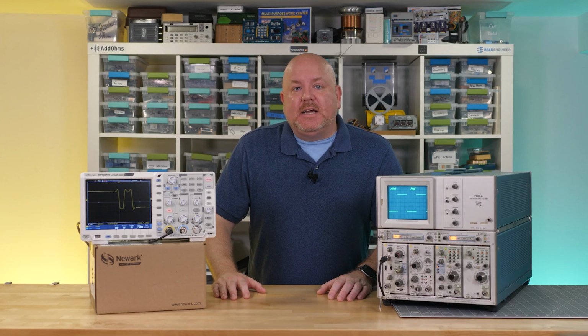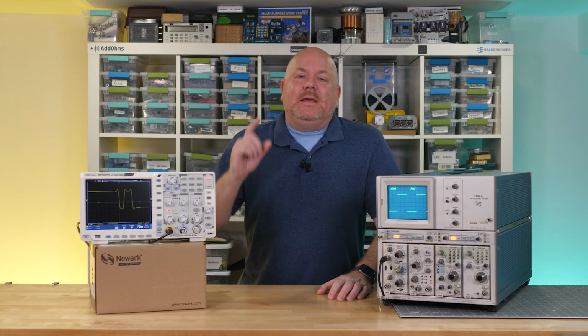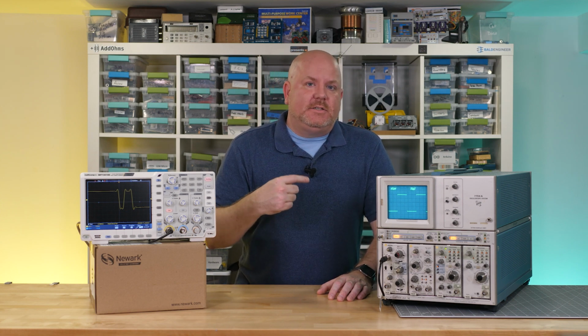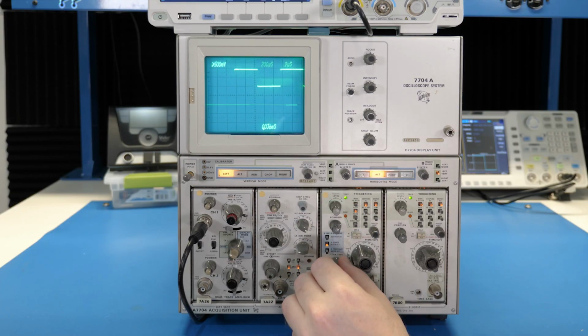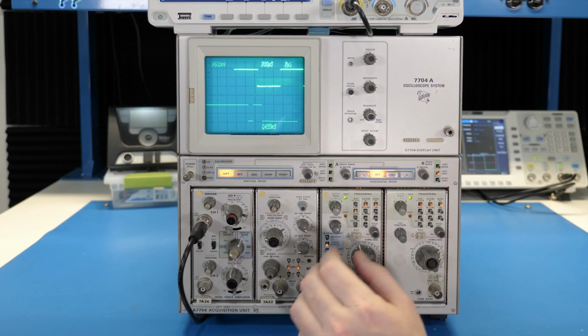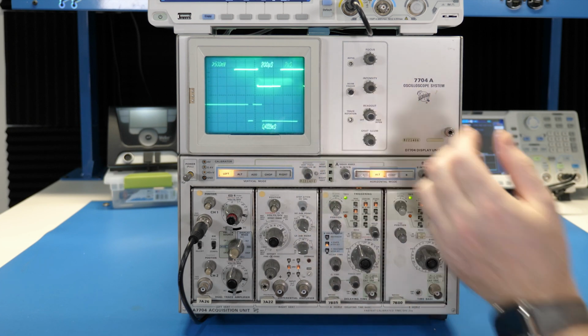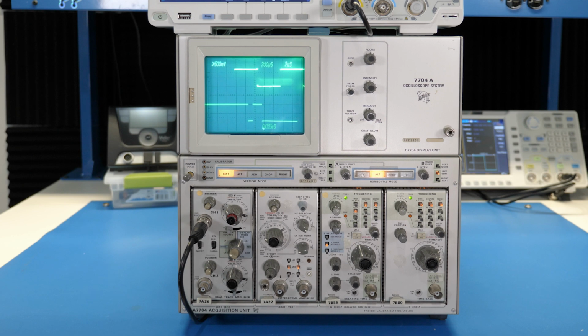In both of these setups, I triggered on a falling edge to make sure that we saw the glitch. But we can't arm the B module fast enough when using the falling edge, so I need to change the A trigger to be on the waveform's rising edge. On the bottom trace, now we see the falling edge and the glitch relative to a longer sweep. With the delayed time base, we now get the same kind of zoom that digital scopes can do.